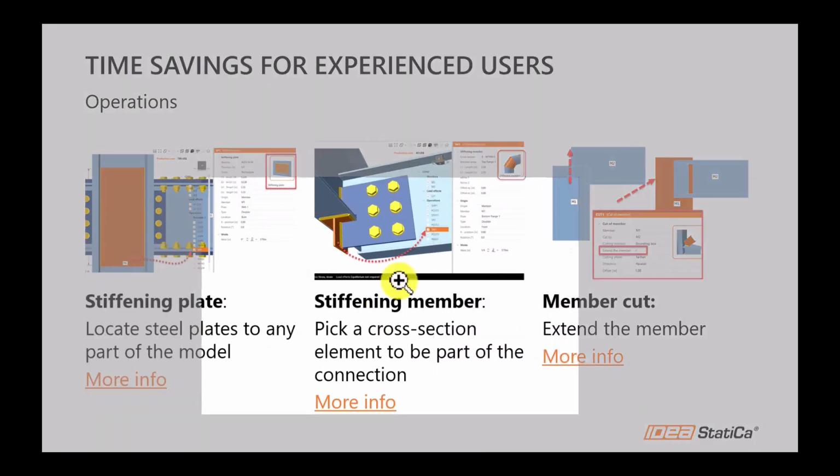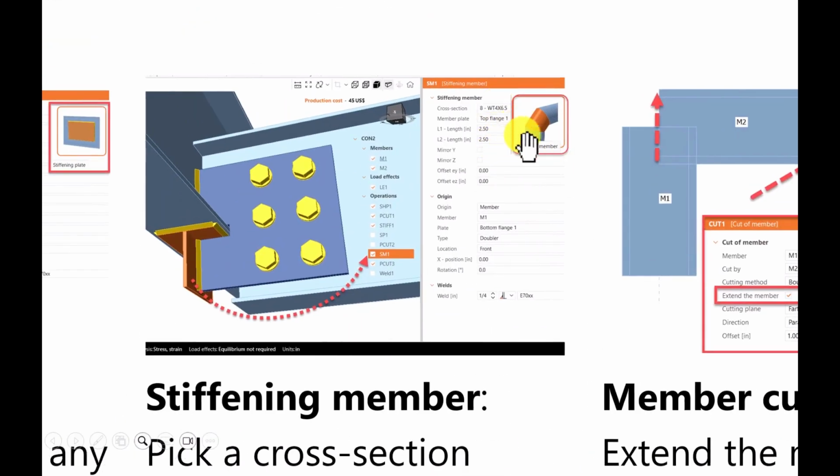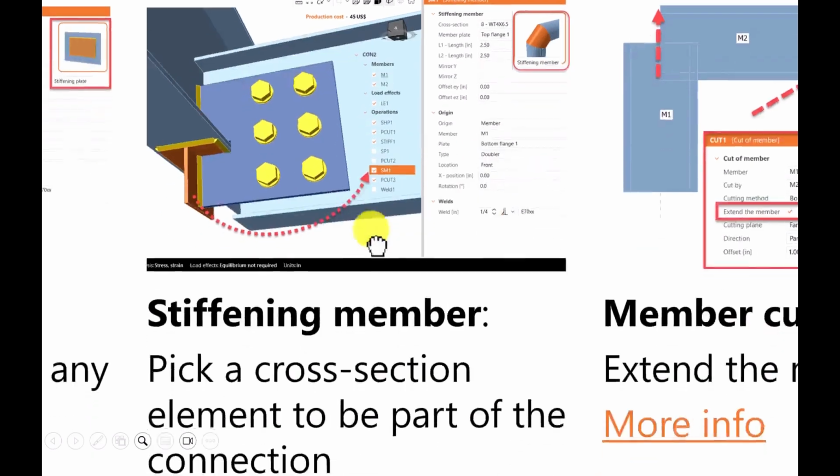The second operation is the stiffening member operation. You can see here the icon, and this will help us to use a cross-section to model a part of the connection. For instance, in the example, it is used to connect a portion of the shear tab to a girder. This member, or this beam, needed to be down 4 inches from the girder top of steel, and then we use this stiffening member operation to weld this portion of the shear tab, right? Again, you can also locate this stiffening member operation from another member or another plate by using this orient option.